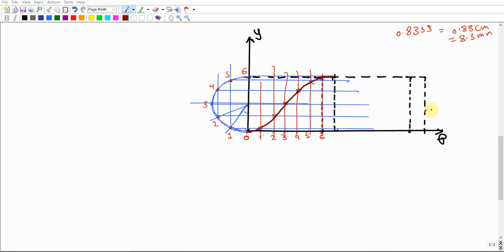You're gonna break it down, divide it into 6 sectors and draw horizontal lines, then draw the vertical lines, locate the center point, the point of intersection. Just repeat the procedure that we did for the simple harmonic motion generation during the rise period. You're gonna repeat it again for the return period. You can do it, right? But try to be smart.